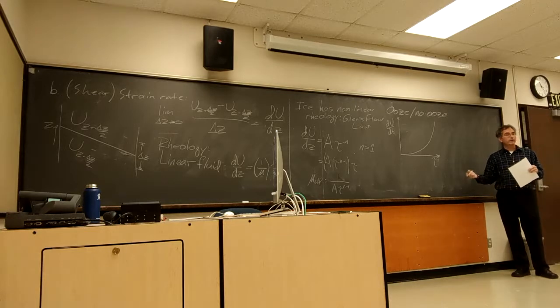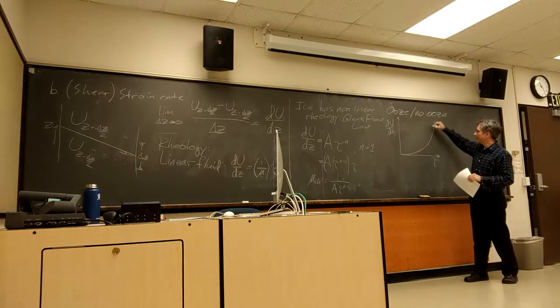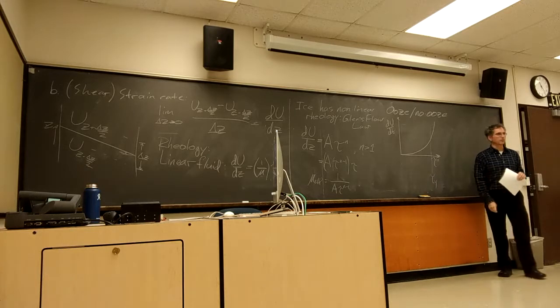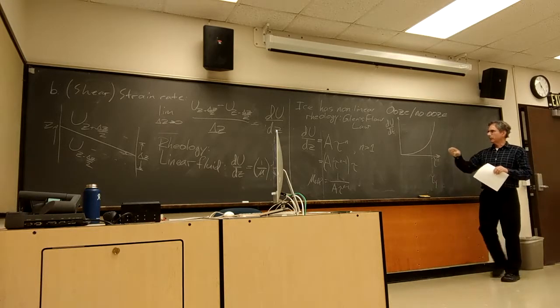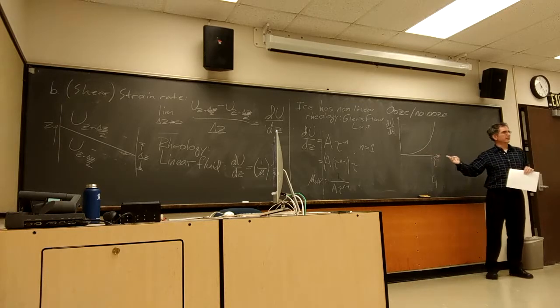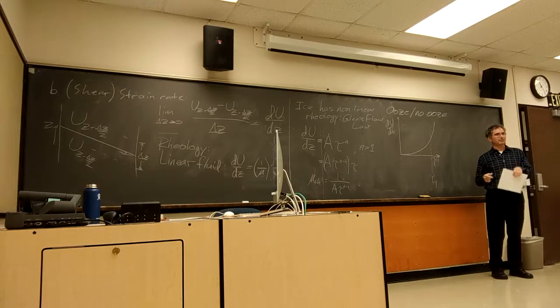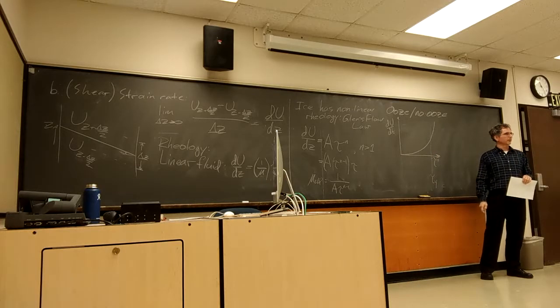And one way to think of that is that the ice doesn't move much at all until we hit some kind of yield strength. I'll call it tau sub y. In effect, we can treat ice, at least as an approximation, as a plastic material, that is, one which doesn't deform until it breaks under this yield strength.